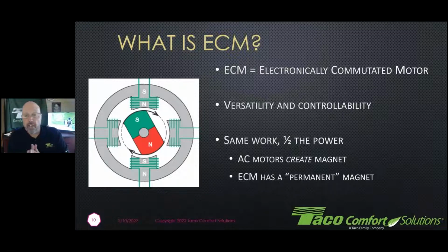So the other thing that helps us get our wire to water efficiency is that an ECM circulator has a permanent magnet built in the cartridge design, rather than creating that electromagnet and using electricity to make this magnet in the middle here on our cartridge in the rotor part. It already is a magnet. All right, so that is one of those things about it.